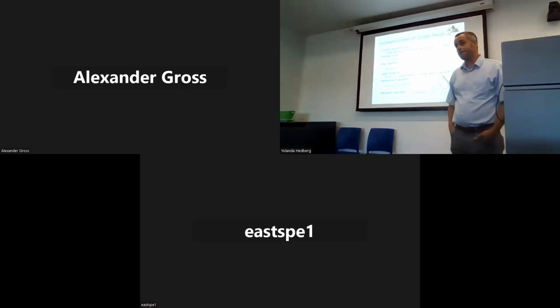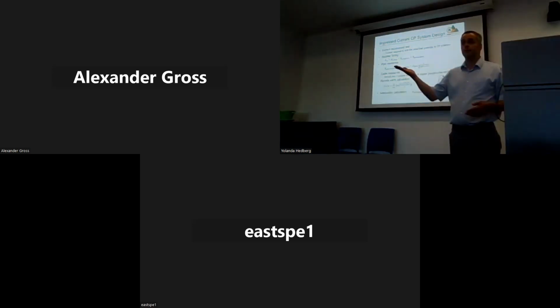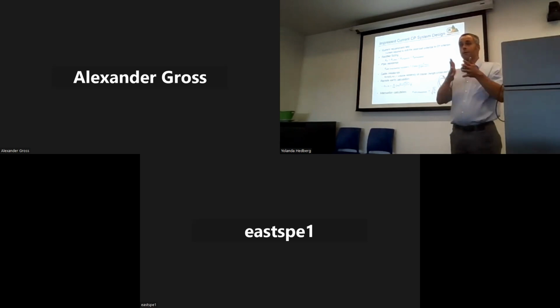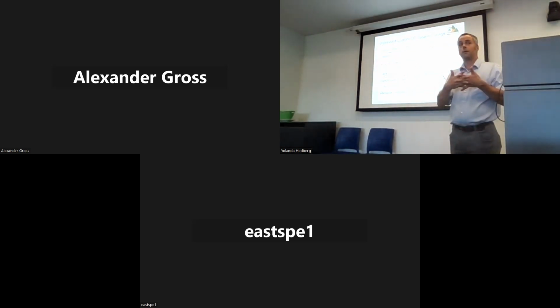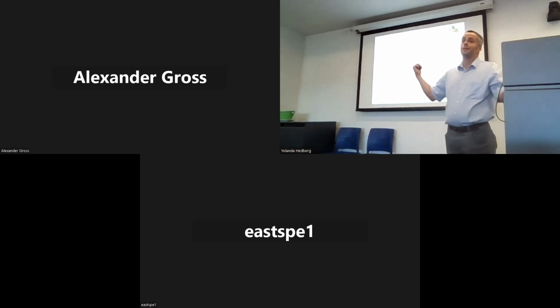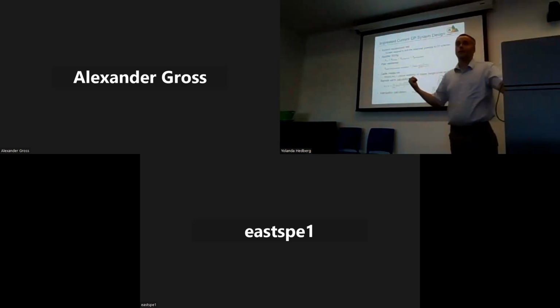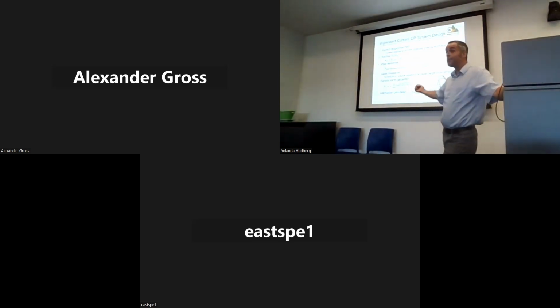But it might affect the adhesion of the coating more, right? Correct. This is why I always say cathodic protection and coatings work together. In the galvanic example, I said 10% bare. What does that really mean? It means that corrosion is 90% stopped because I have 90% protection due to my coating. Cathodic protection has to pick up the slack for the other 10%.